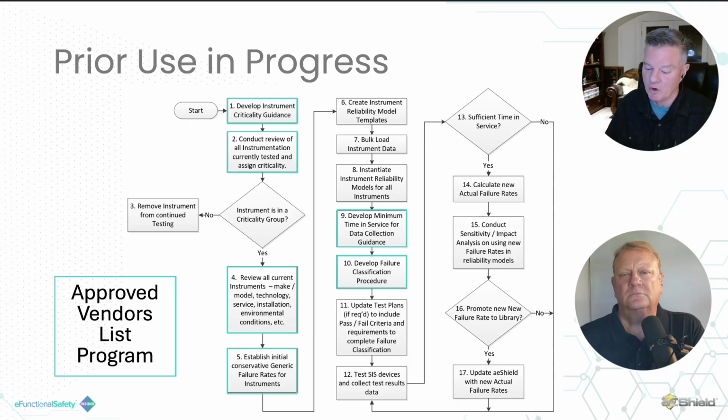And then once we have our own failure rates, you're going to identify bad actors, things that have dangerous undetected failures that are exposing the business to risk that could escalate if other layers fail. So you're removing that risk from the business, but then you're also finding where your initial assumptions were conservative, and you can start extending testing without putting the business at risk, whether it's commercial risk or actual safety or environmental risk. You have direct line of sight on all that.